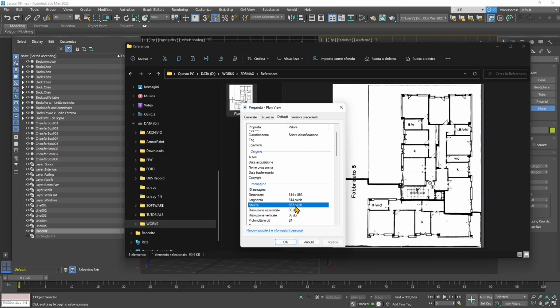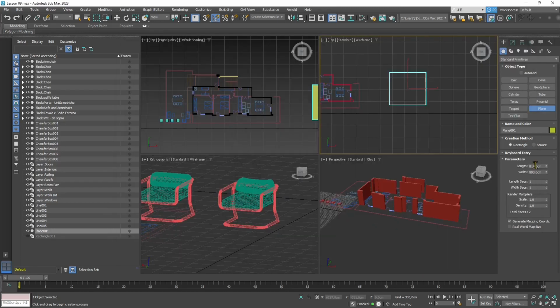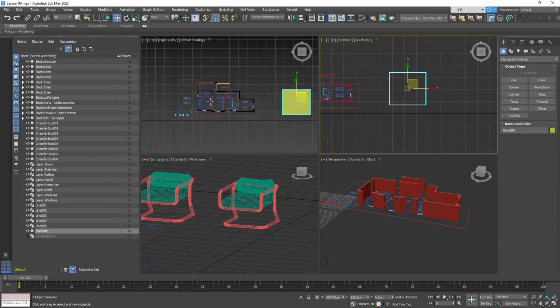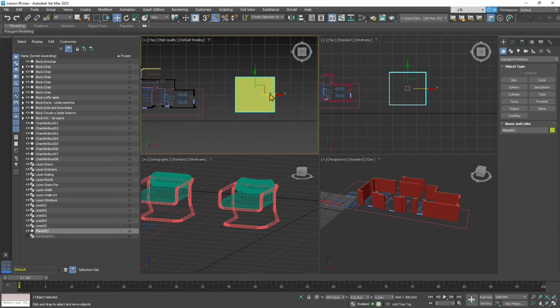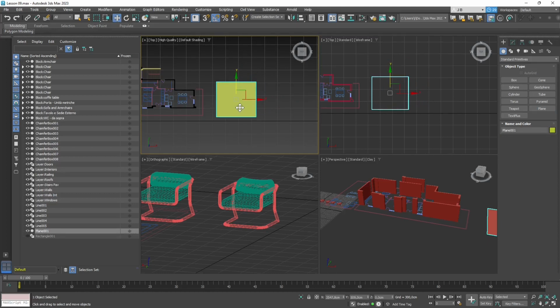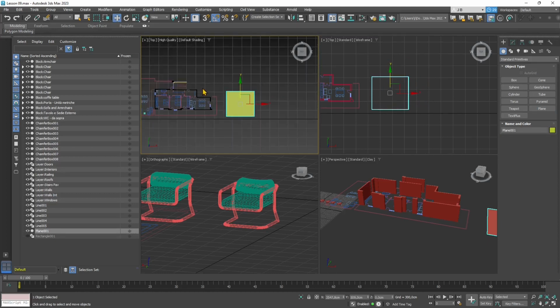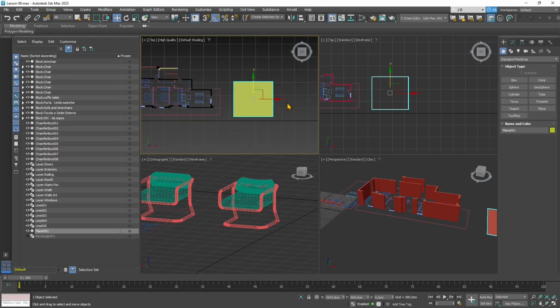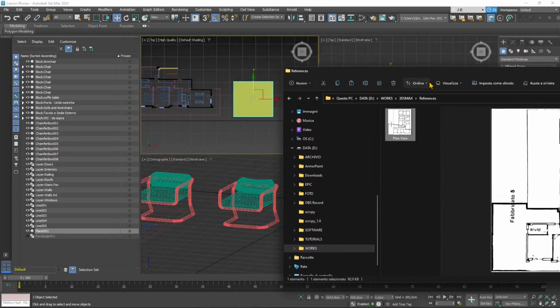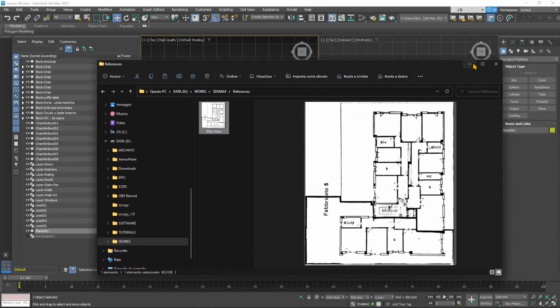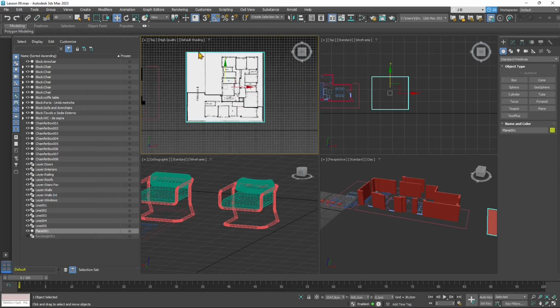So that's important. Otherwise, it's going to cause issues later with all the different measures. So make sure that you have the correct proportions. That's the most important thing. You can always take care about the scaling later. So I'm going to show you also to put everything in scale, but first of all, you need to do this, height and width match with the plane and the image. And now I can click and drag, and I will click and drag directly onto that object. So you can see that I place my image just right on top of that plane.